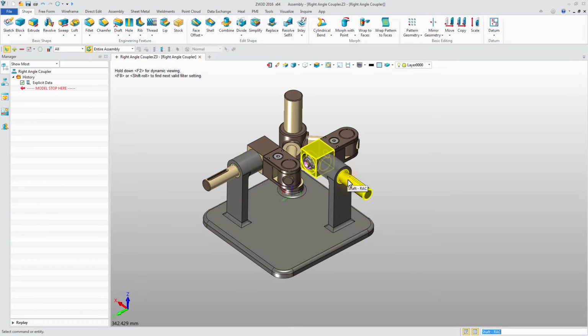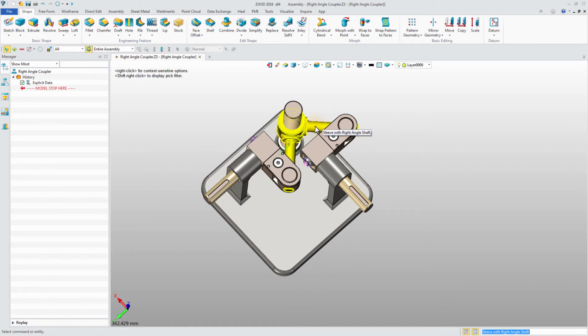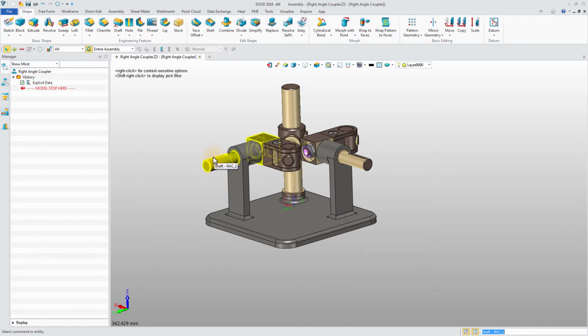When the shaft rotates, it forces the bolt attached to it to rotate as well. And since the pivot is attached by a rotating joint to the bolt component, and by a socket to the shaft at the core of the device, it is able to conduct the motion to the sleeve, and in the same pattern of connections, the sleeve is then able to transfer the motion to the other end of the coupler.